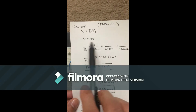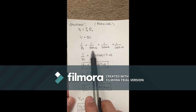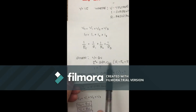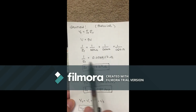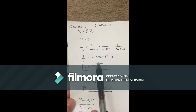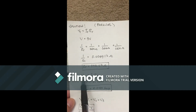We already know that we have a 9 volt battery source, and each resistance is at 680 ohms. By following the formula, we get the total resistance of the parallel circuit, which is at 226.67 ohms.